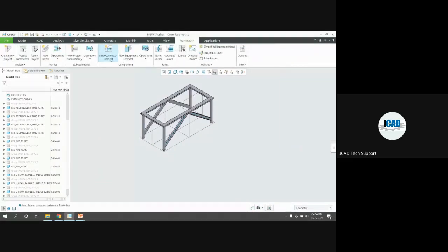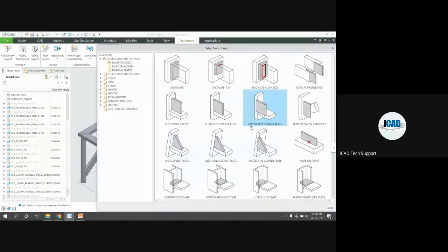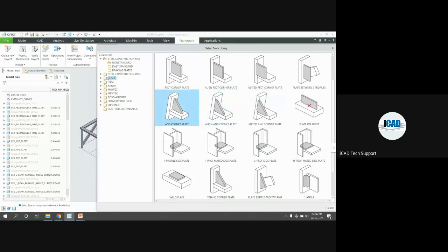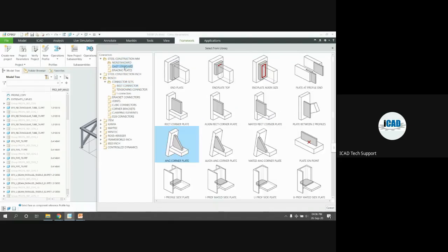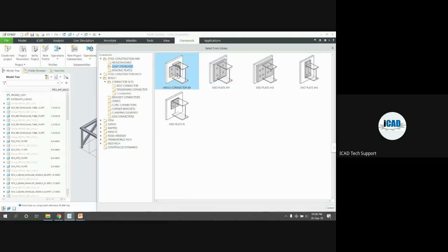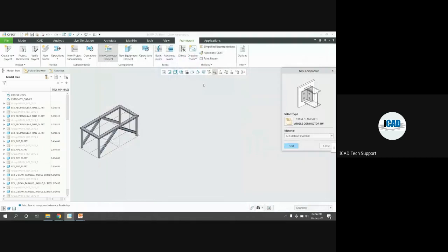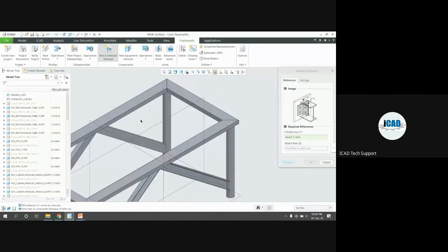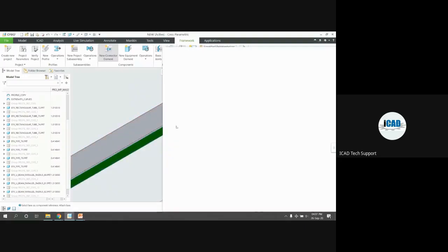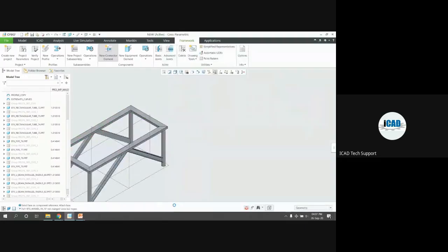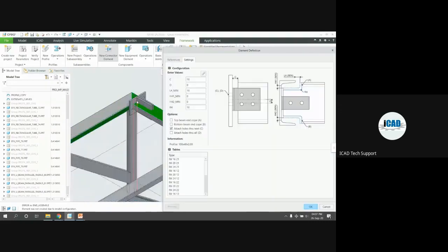In the framework again for the connector elements, as angle plate, joint plates. Now we can use the standard elements like angle connectors. Click on double connector, click on next. Here I want to add the angle connector. The first profile will be this one and second profile will be this one. Because if I go directly with preview, the size will get disturbed.